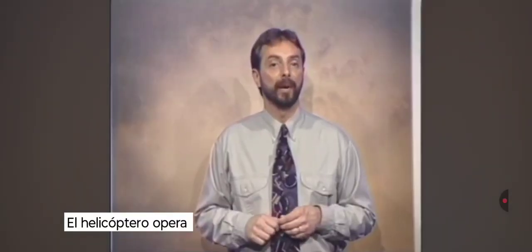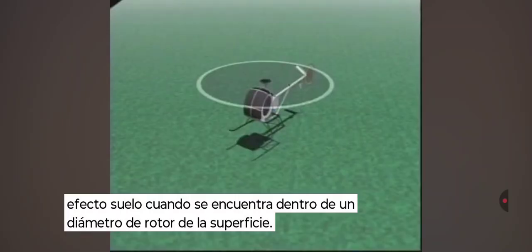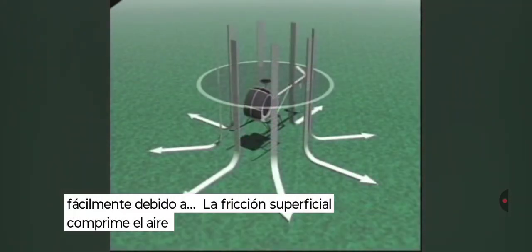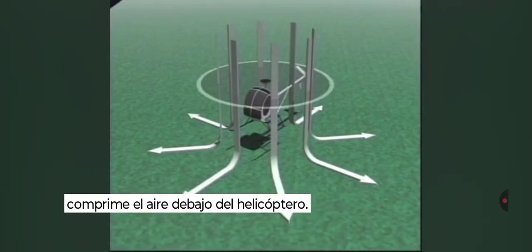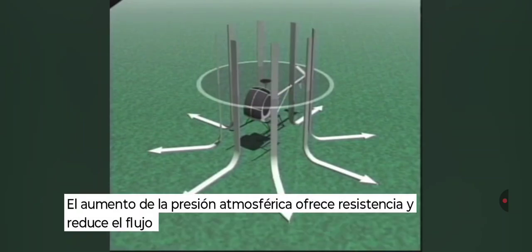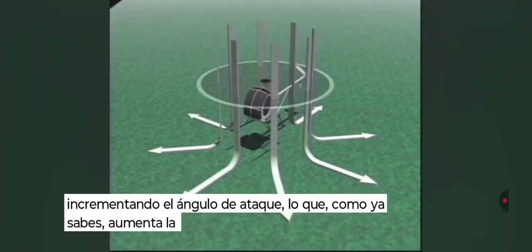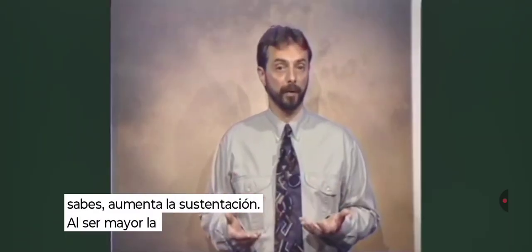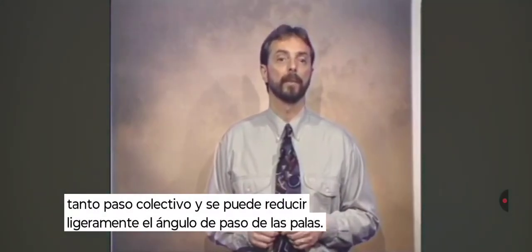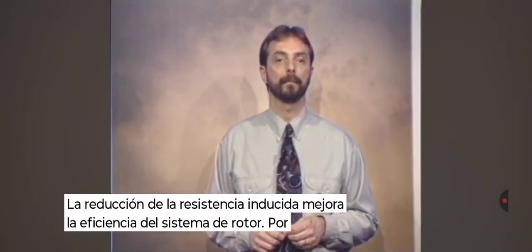The helicopter is operating in ground effect whenever it's within one rotor diameter of the surface. The rotor downwash can't disperse readily because of surface friction, making the air beneath the helicopter compressed. The increased air pressure resists and reduces the downwards flow of air, increasing the angle of attack, which, as you know, increases lift. Since lift is greater, we don't need as much collective and can lower the blade pitch angle a little. The reduction in induced drag improves the efficiency of the rotor system.